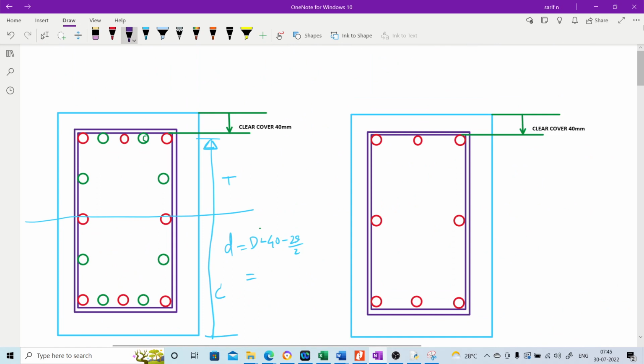So as you know, if you look here, the dimension here is 400 mm. Okay, that means if you go for center to center of the bars, this will be greater than 300 mm. So the code says in no way should the distance between the two parallel legs of the stirrups be greater than 300 mm. So in that case, we will have to provide cross ties.